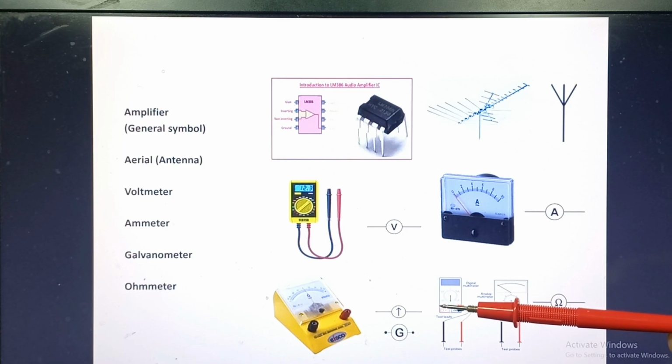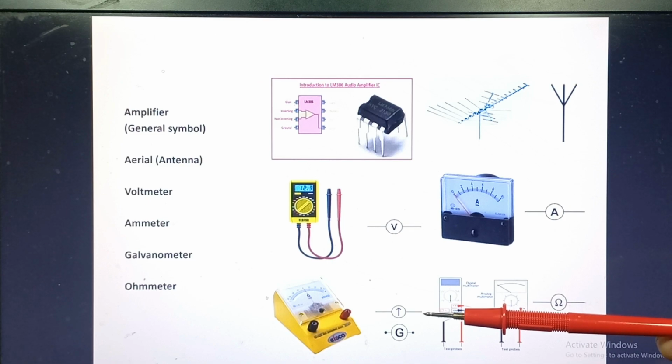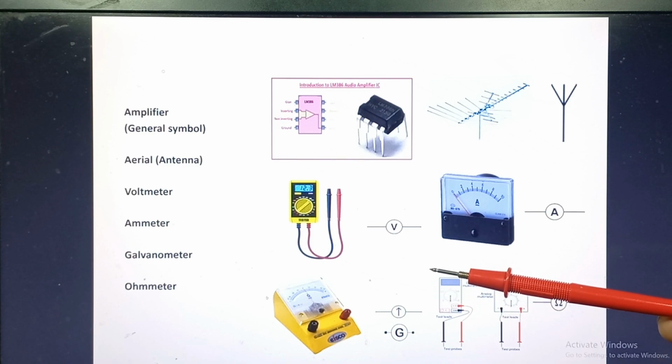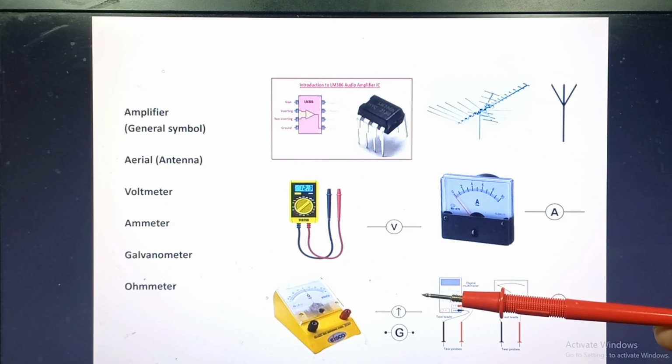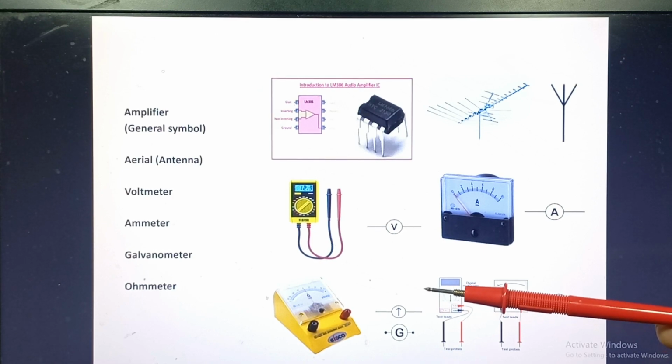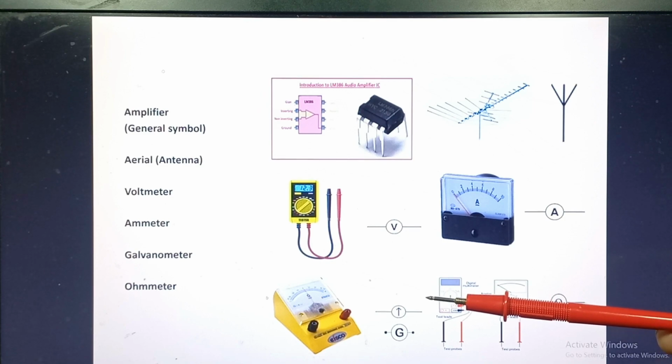If the meter is switched to 20 volt DC, for example, then 20 volt is the maximum voltage which can be measured. This is sometimes called 20 volts FSD, full scale deflection, where FSD stands for full scale deflection. For circuits with power supplies of up to 20 volts, which includes all the circuits you are likely to build, the 20 volt DC voltage range is the most useful.